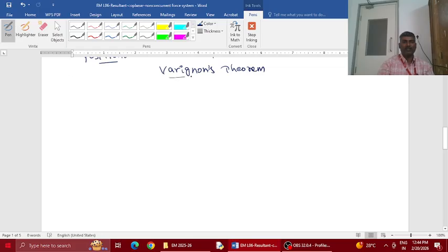Okay. So what is Varignon's theorem and how it is going to help you? I'll say it in simple way, like moment of resultant means resultant into the distance. Moment of the resultant will be equal to sum of moments from all the given forces about the same point. Okay. So in our case, there are three forces, right? So I'll call it as F1, D1, F2, D2, F3, D3. Okay.